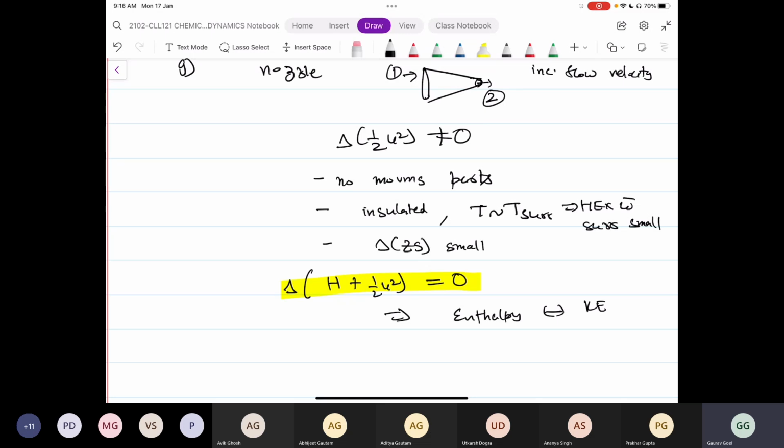You will need to add work, and then your answer becomes somewhat independent of the inlet pressure and temperature conditions. Okay, you just modulate the work input, and by modulating the work input, you can modulate the exit velocity. So depending on the job, you might use a nozzle or a pump to increase flow velocity. That will all depend on how much velocity increase is required, what are the inlet conditions you are dealing with, and what are the target outlet conditions. So all those questions would lead you to selecting one over the other.